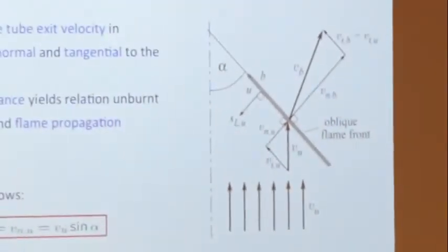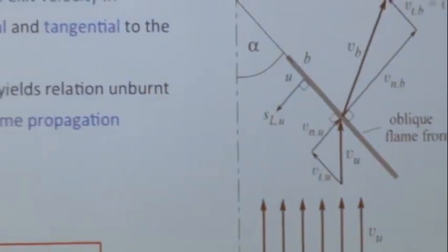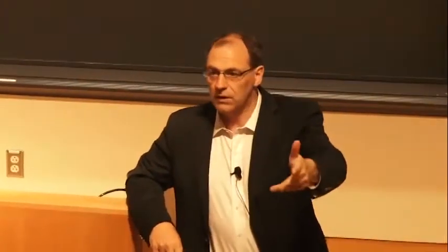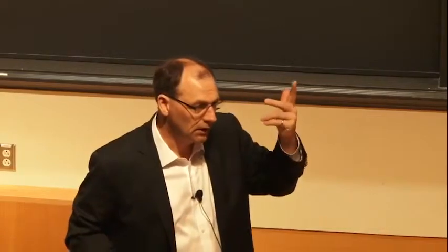What's interesting here is how we define this value that we call burning velocity. You could say that it is the speed of this flame relative to the gases surrounding this flame. Now you have a different velocity ahead of the flame and behind the flame, so you need to say what relative velocity you mean.